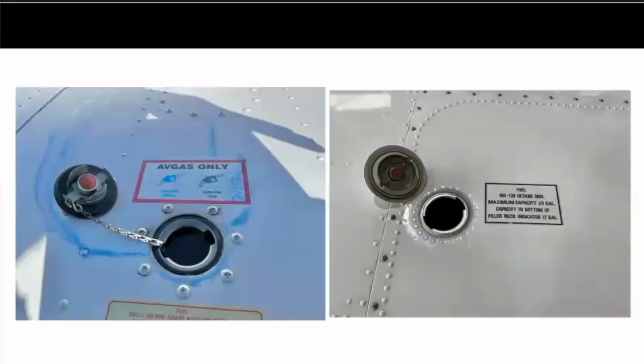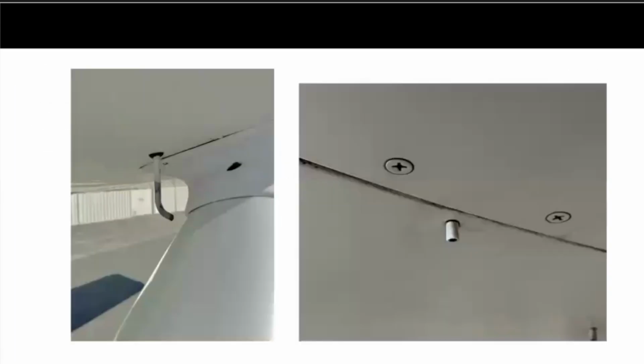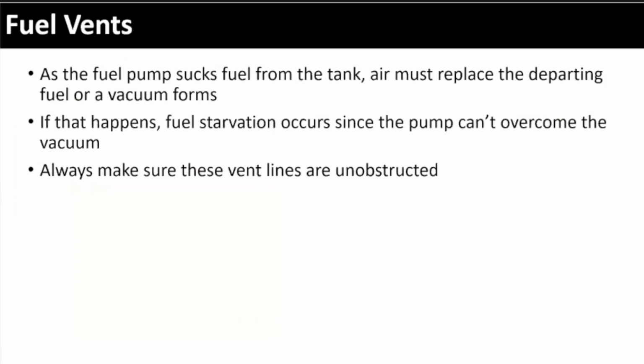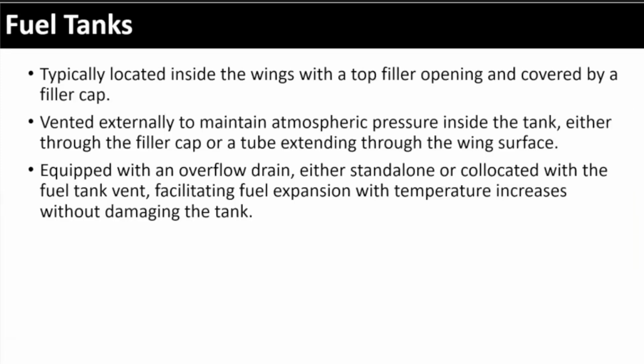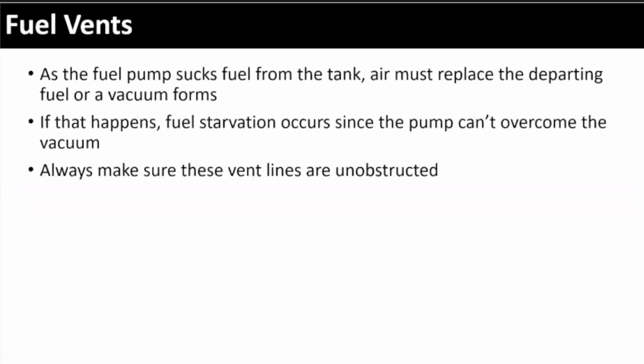And you'll see, I think he's got a picture here. Yeah. Underneath the wing, there's drains, right? So if there's overflow, that fuel gets to a point at the top of the tank where it will actually drain out to relieve that pressure. Make sure you're not exceeding the pressures in the tank. Okay. Make sense? Okay. So we want to make sure we've got the fuel, make sure it doesn't get too much pressure in the tanks.